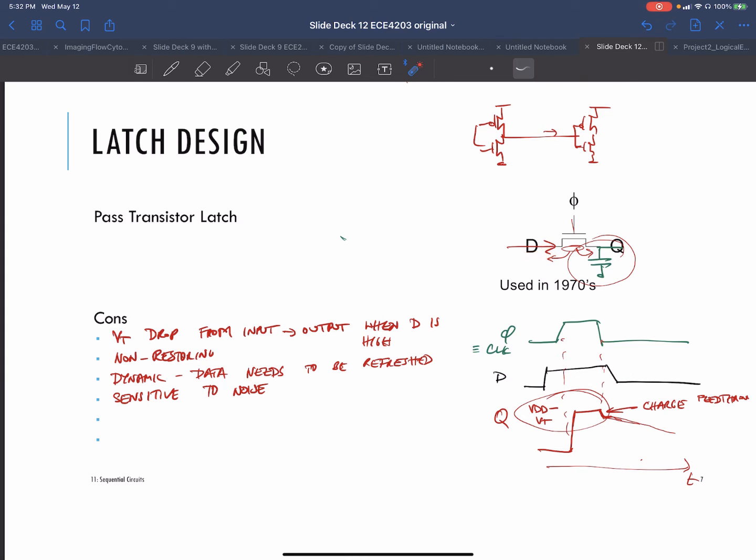Here, it is possible that you have overshoot or undershoot, as you guys remember, like your input voltages don't necessarily, whether it's going up, it's not necessarily going to look absolutely clean. As you're seeing in project 3 or in the projects that you're doing, you get glitches and all that stuff. And going to the source, driving a diffusion, if those are big enough, they can start causing some problems. So you have to be worried about that.